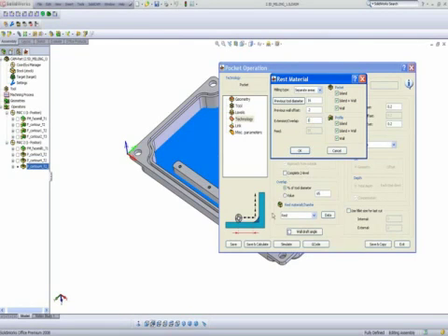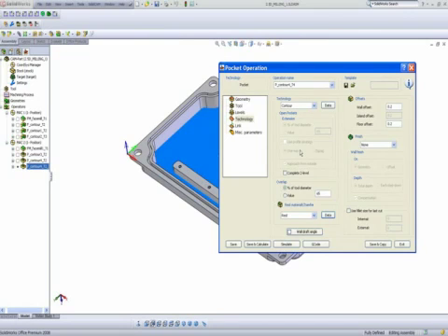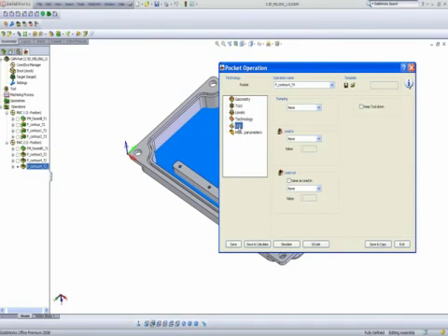What this does is very simple: right now I'll be cleaning in the area where the previous tool did not. But I would want it to start a specific distance away from where that area could not clean, so as to avoid having a mark on the part itself. I'll simply say OK. In my link area now, I will use a lead in, something I could not do before.